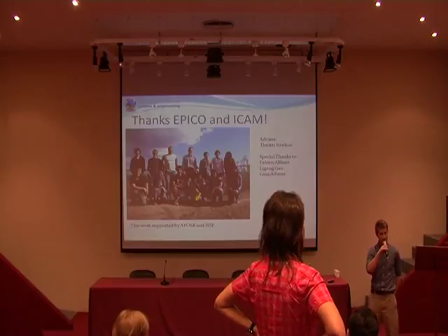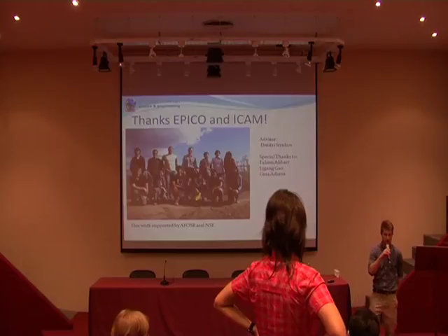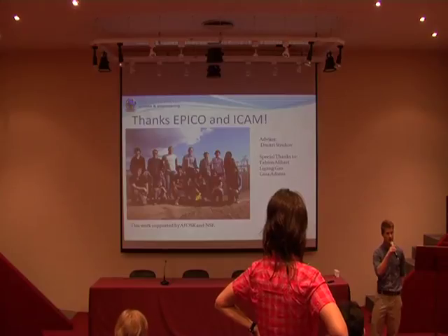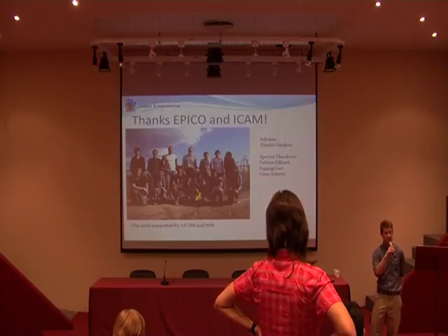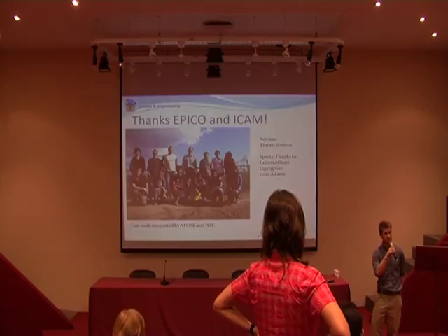In general, I deposited everything at room temperature. And so, in general, if you do your depositions below 300 degrees C, you should have amorphous films of titanium dioxide, particularly since it's a tetrahedrally coordinated solid. So I didn't do XRD on the films or anything like that, if that's what you're asking, as a function of the change in flow rate.